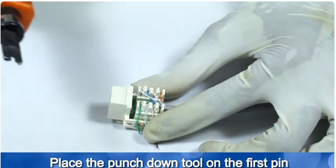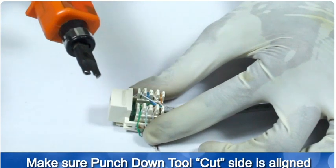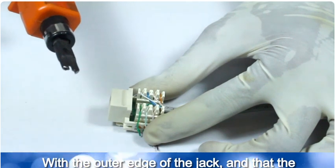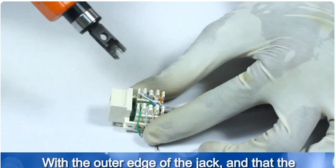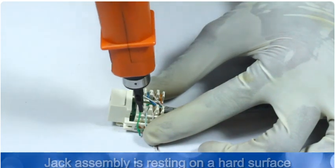Place the punch down tool on the first pin. Make sure punch down tool cut side is aligned with the outer edge of the jack and that the jack assembly is resting on a hard surface.